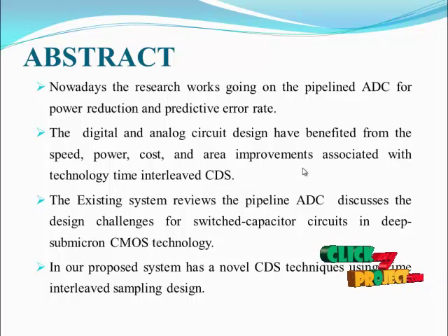We propose a novel phase dependent gain transient CDS technique, which is another efficient way to reduce prediction errors without using additional capacitors. By utilizing a very low gain op-amp, we reduce the prediction error by providing a slightly higher DC gain during the pre-amplifier phase, although this is still much lower than the gain of conventional op-amps commonly used in pipelined ADCs.